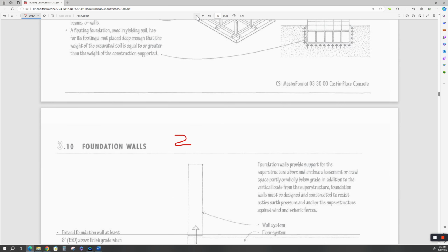If you're using bar joists, which are trusses, then you can embed steel base plates anchored to the concrete foundation or wall and set the bar joist on them. I would embed steel plates, and then the upper flange of the bar joist, the upper chord of the joist, you can come in and weld them. Okay.